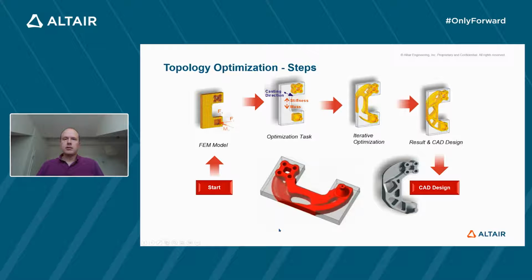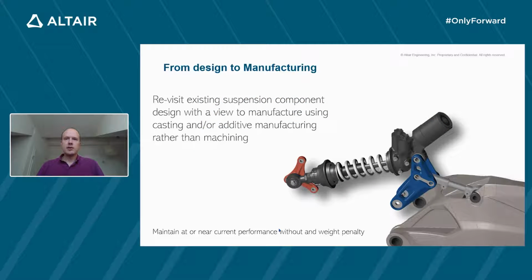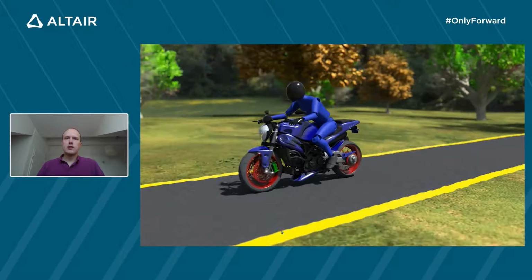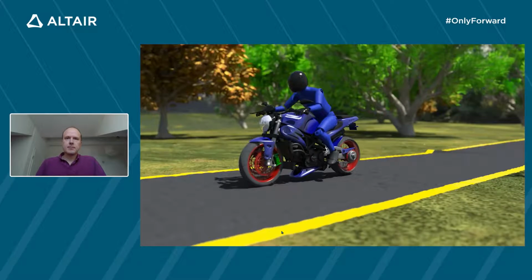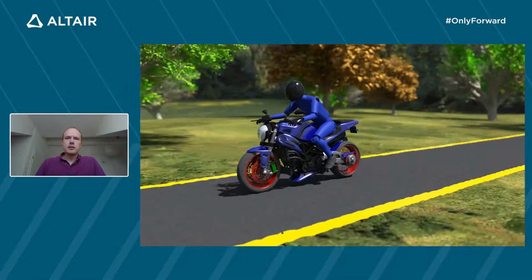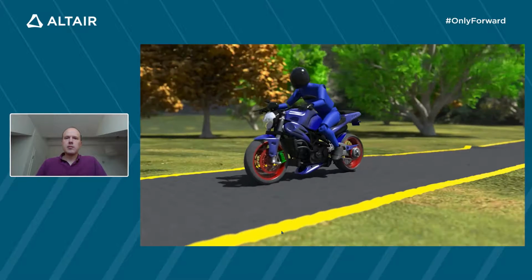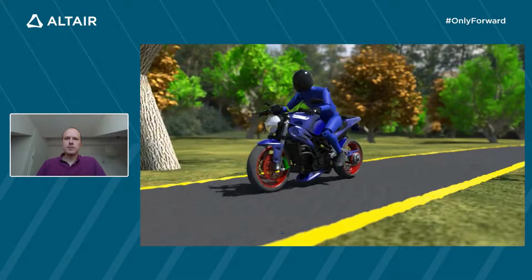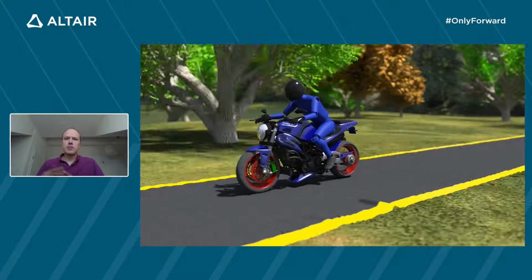All right, now I will show you this on the suspension example. So the blue part is the one that I would like to optimize. So that's the part that will then be used in the topology optimization. But the first step, as mentioned, is a motion analysis to determine the correct forces for this assembly. And the motion analysis will be the sort of analysis that you see here, which is a rendered simulation result. So in the motion analysis, you basically give the software a dynamic event, for example, a road event leading to motion in a structure.